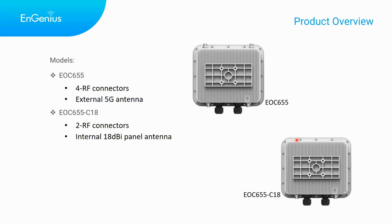What about external antennas? Will EnGenius provide solutions for point-to-point or point-to-multipoint? Do stay tuned for that. But for now, the ones that we have use the internal antenna. For external antennas, this one is still in planning. But what's nice is that since we have N-type connectors for the EOC series, you can use any antenna so long as it's 5 gigahertz and supports MIMO. With the current lineup being 2x2 MIMO, a 2x2 MIMO 5 GHz antenna should be able to work with our model, regardless of the brand.